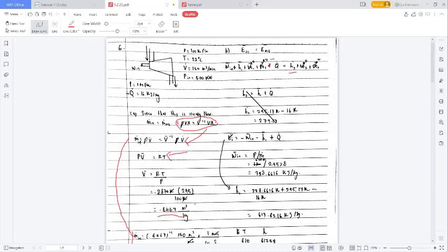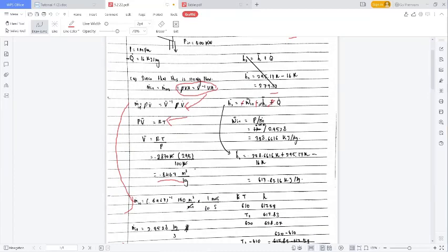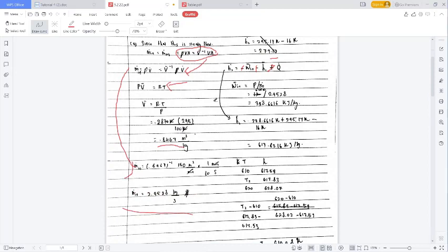So we can simplify this into specific enthalpy 2 equal to, this would be plus and this would be plus, this would be minus: work in, specific work in, plus enthalpy 1 minus Q dot. It is referred to as heat loss. Work in is equal to power over mass flow rate, so this is the equation that you need to take note of. Power is 500 kilowatt over the mass flow rate 2.9528. Thus we get 338.6616 kilojoule per kg.